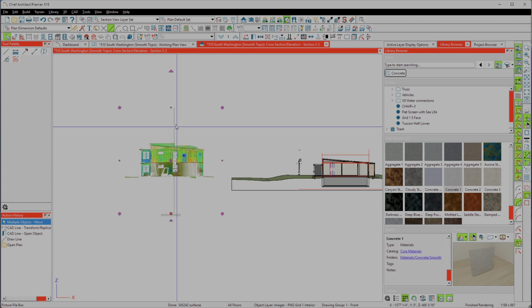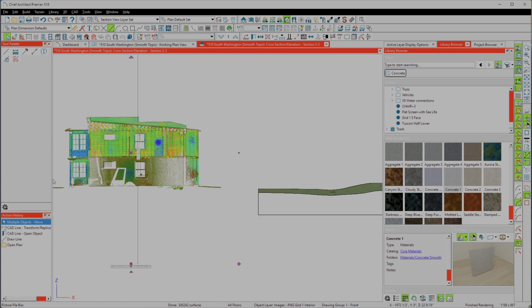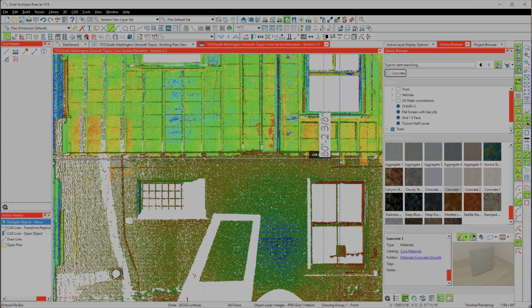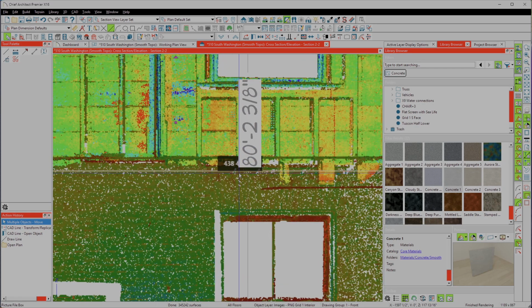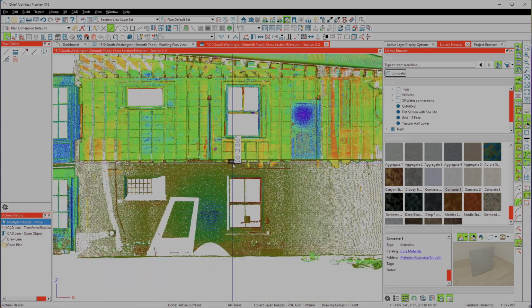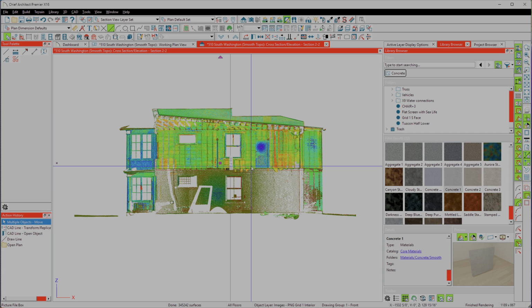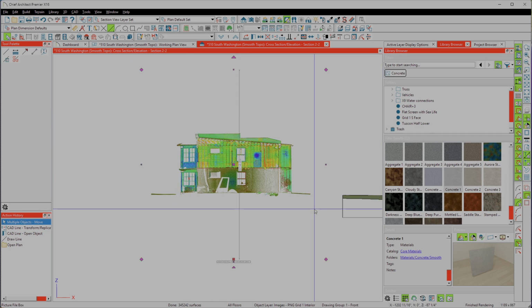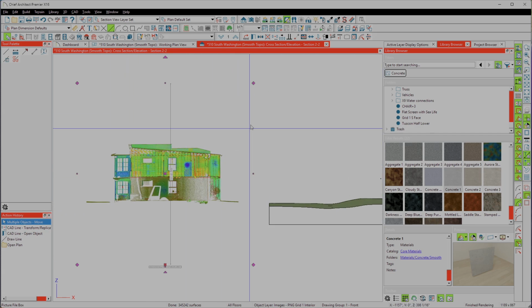So I've got this scaled in, and I did a video on how to scale these PNGs, which is basically I draw a line along this once I've brought it in, and then I simply tell it to scale it to that number that was there, and it snaps to place. So now that I've got this to scale, just bring in a PNG, do your scaling, and then once you've got a scaled PNG, you've got this box, and that's what we're going to use to create an image.